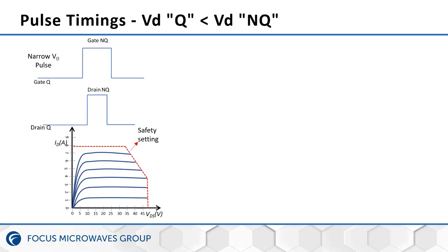Now, when we are talking about IV sweeps, there is another important point that we need to take care of, which is defining the pulse timings for our measurement system. Auriga allows us to set multiple different settings and different delays for both the gate and the drain pulsers. It also allows you to control the quiescent and non-quiescent voltages within these pulser heads.